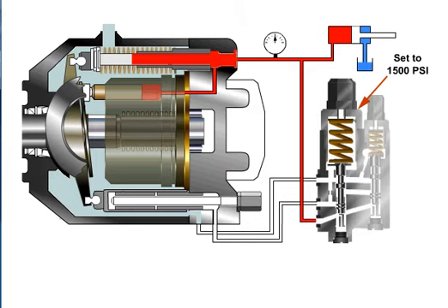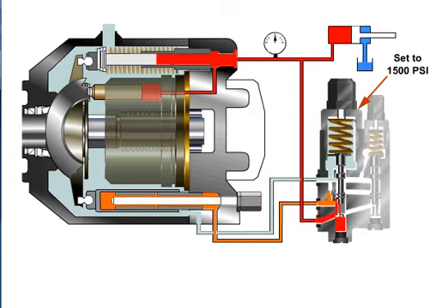This pressure forces the compensating spool up, allowing the pressurized fluid to energize the de-stroking piston and push against the swash plate, forcing it to a vertical position. With the swash plate vertical, the pump is now de-stroked and the pressure at the outlet port is maintained at a constant level. A very slight amount of flow is produced to maintain de-stroke pressure. This flow is bypassed into the case and carried back to the reservoir through the pump case drain outlet.